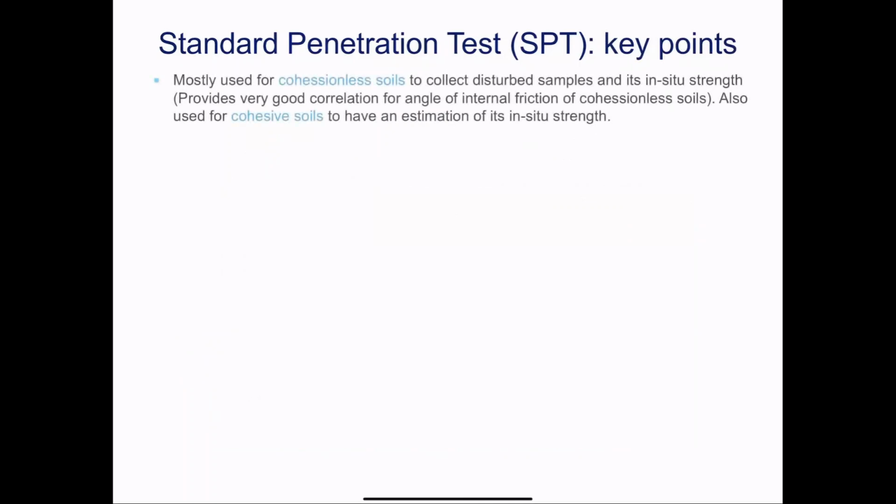And we ended off here with these few points. In summary, SPT tests are quite ideal for granular soils to determine the in situ strength. And we'll talk about how to determine the in situ strength based on the N value later on. There are significant volumes of literature and correlations in Hong Kong, because in Hong Kong, we are quite data rich, right? And we're quite dense. We have lots of geotechnical works, so we have lots of data to use to correlate with friction angles for cohesionless soils.